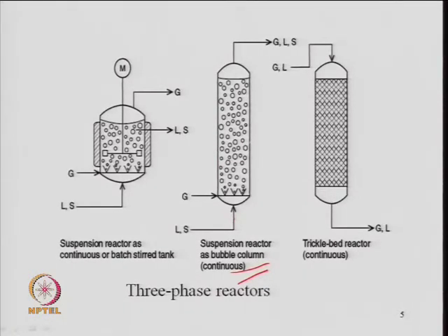This is very important, especially in the hydrotreatment reactions in the refinery or petrochemical industry, or advanced air oxidation process. Trickle bed reactors are used, right. So, here again you have gas and liquid coming from the top, and then it is coming down from the bottom. So, gas hold up, liquid hold up, then contact between the gas, solid, wetting, wettability. There are many factors involved which decide the efficiency of the process, right.